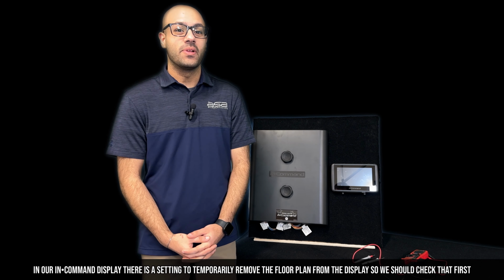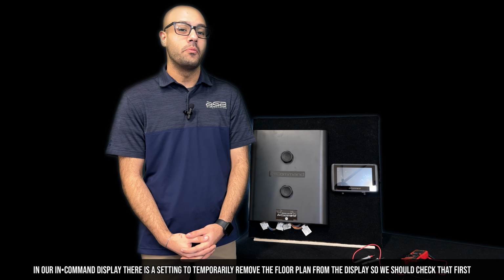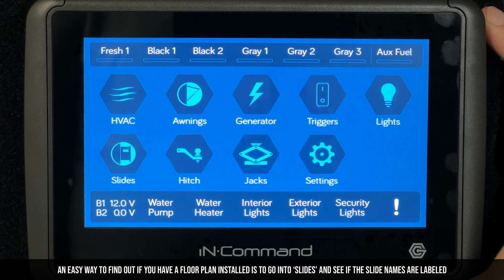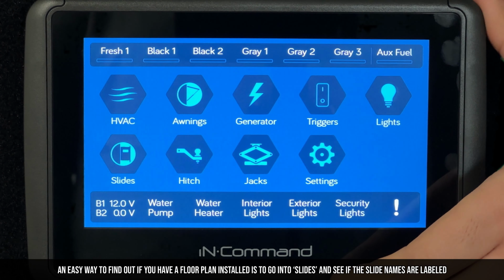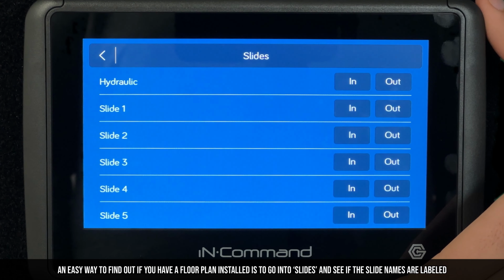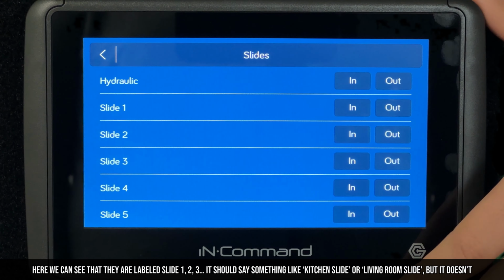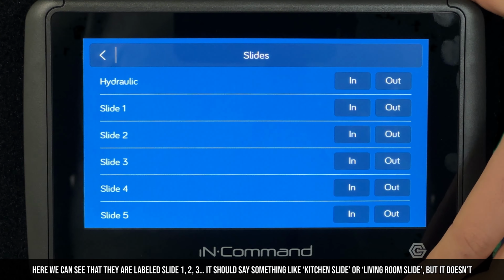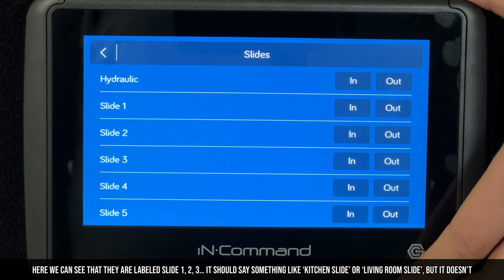In our InCommand display, there is a setting to temporarily remove the floor plan from the display, so we should check that first. To find out if you have a floor plan installed is to go into Slides and see if the slide names are labeled. Here we can see that they are labeled slide 1, 2, 3. It should say something like kitchen slide or living room slide.